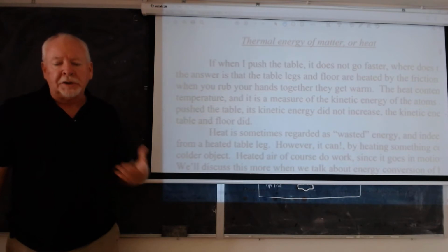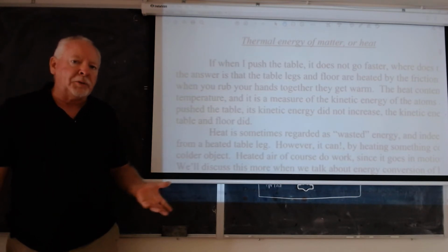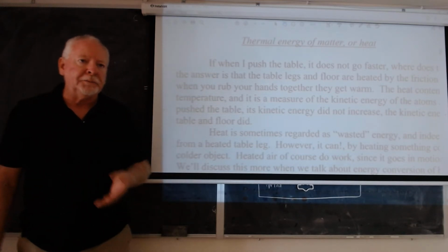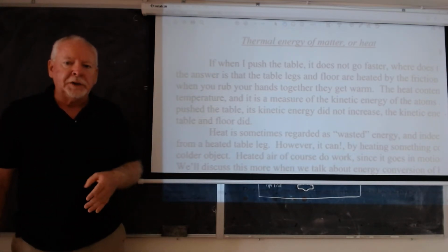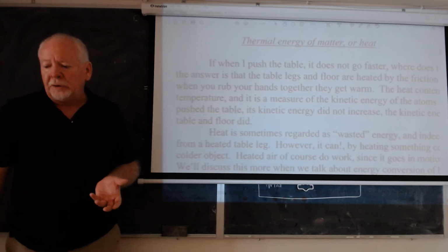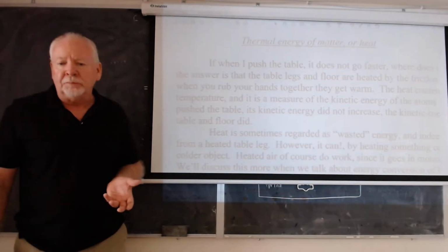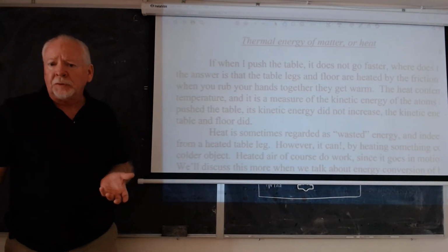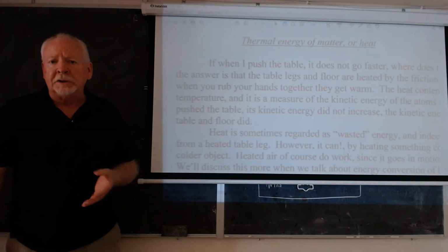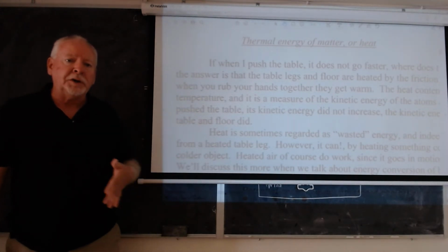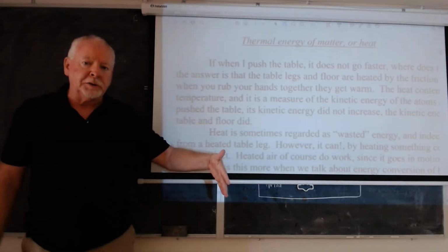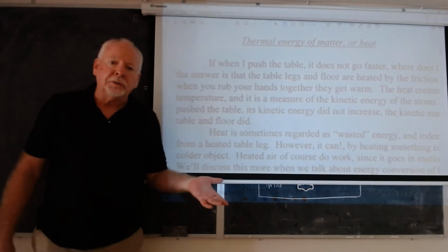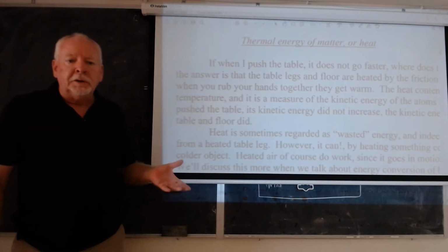One of the ideas behind the second problem of homework 1 was to get you used to thinking of fuel consumption per unit time as a form of power. You're burning through a lot of gas, so you're consuming a lot of power, and that power has to end up somewhere. Because you're going at a constant velocity, your kinetic energy is not changing, and where it goes is into heat.